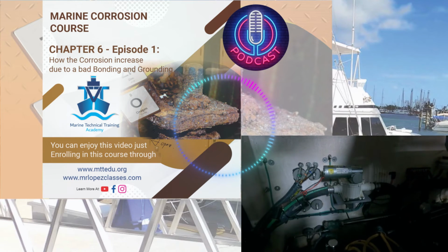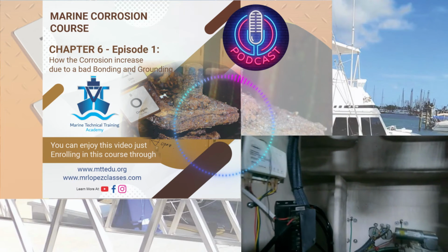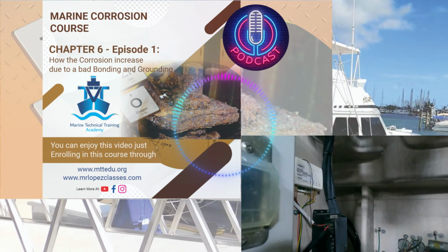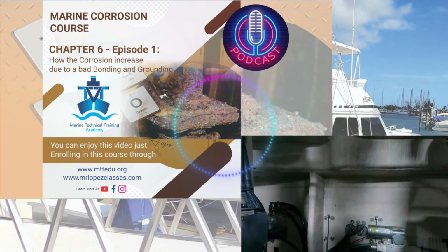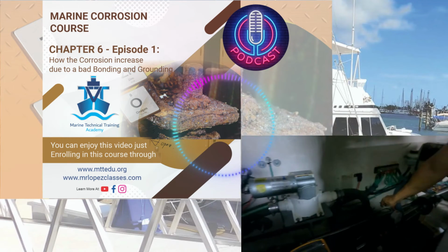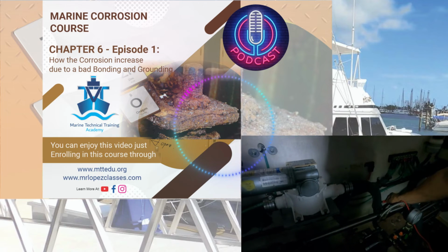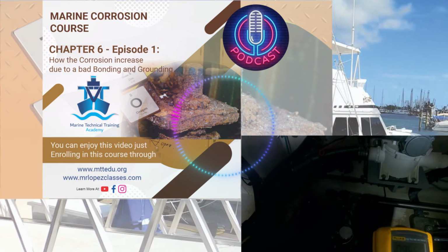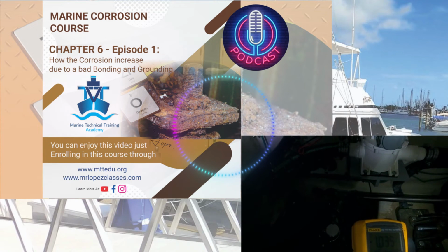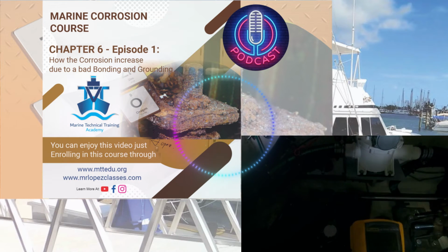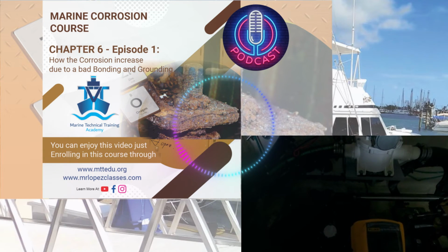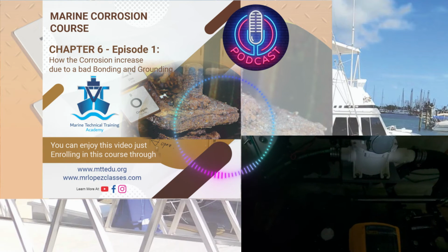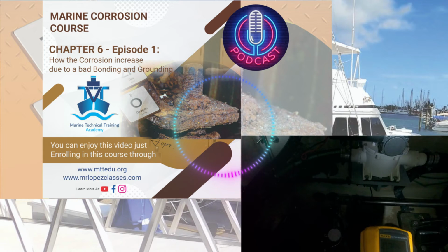Now I am going to explain the procedure to verify if the galvanic isolator is working properly. The first step is to disconnect both terminals of the galvanic isolator. With a piece of wire, make a short in order to discharge the galvanic isolator completely. Internally, the galvanic isolator has capacitors and a couple of diodes. When you do the short, you discharge the capacitors. Right now, the galvanic isolator is completely discharged, and we are going to check the galvanic isolator step by step.